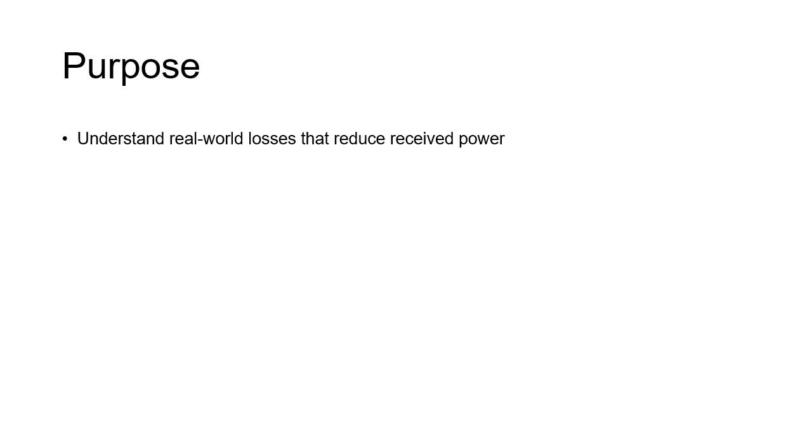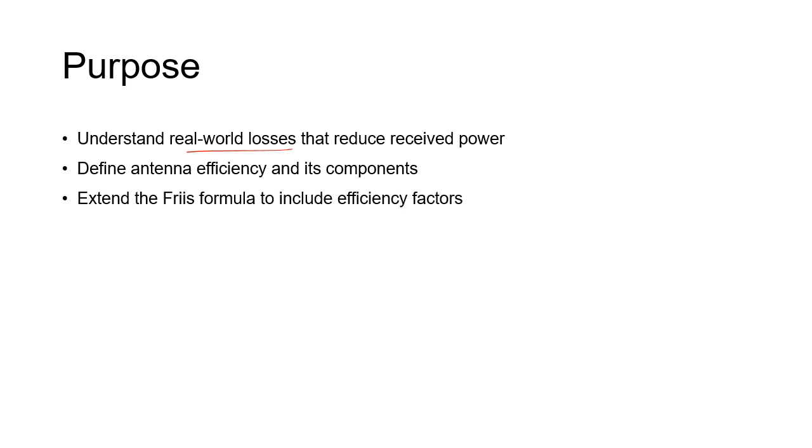So the purpose of this presentation is to understand losses in the real world that affect the received power. Then we will define antenna efficiency and its various components, and finally we'll extend this to a more generalized form of the Friis formula by including these loss factors.